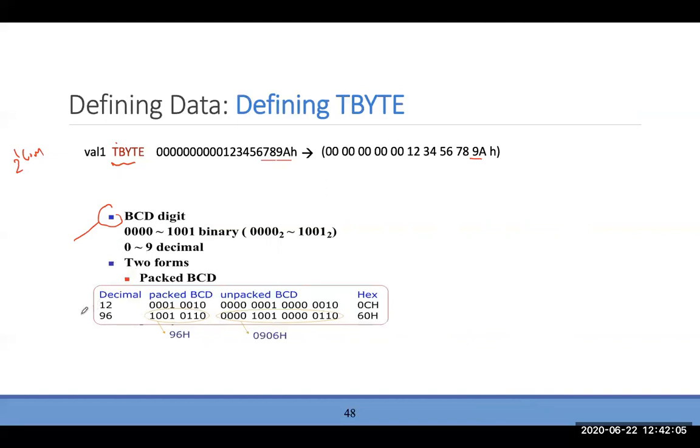And when we talk about BCD, we have 2 types of BCD. Okay, BCD that is packed and unpacked. The packed BCD is just like if you have a 12 right here, so you're just going to have 0, 0, 0, sorry, 0, 0, 1, 0, and then you have 0, 0, 0, 1. So this is 1 and this is 2, that's 12. Okay, so with 2 hexadecimal digits, you can represent any decimal number, right? That's more than enough. Or unpacked, that's going to take the entire byte. Why do I have to waste this space if all I need is just 4 bits, right?